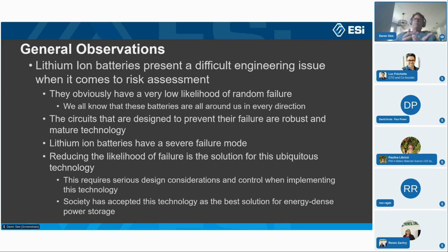The reason they can't use aluminum as the negative electrode and have to use more expensive copper is because aluminum is a less noble metal, and it will start to participate, like the lithium ions, in the discharging reaction, and then you'll have corrosion of the pouch and eventually holes in the pouch, and then electrolyte leakage. And this is something that we've analyzed and found in the field in the past.